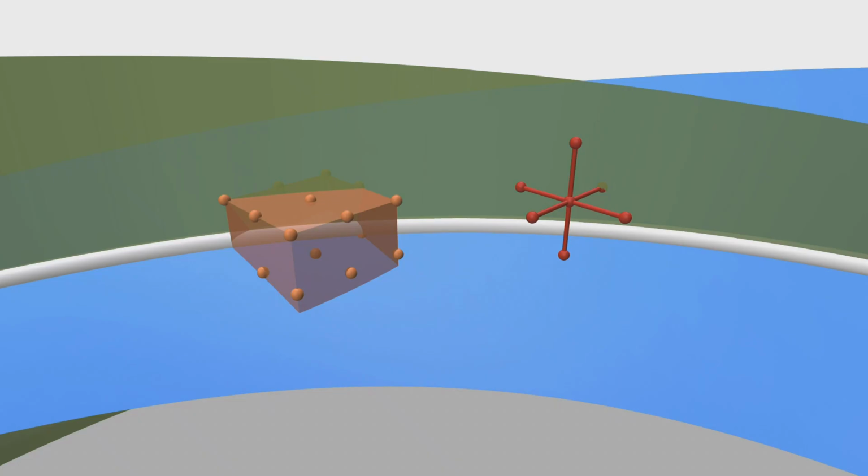So you enforce the boundary condition equations if that grid point crossed. And when I say crossed, it's with respect to what we call the stencil director. So the stencil director for an interpolation stencil is the interpolation query point, and the stencil director for the finite difference stencils is the closest point of the stencil center.